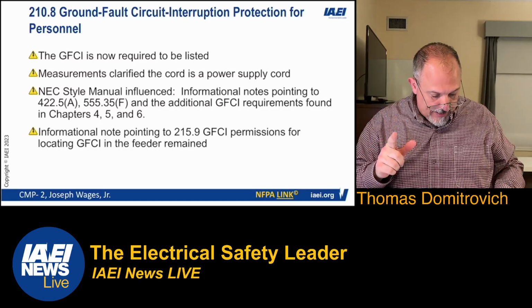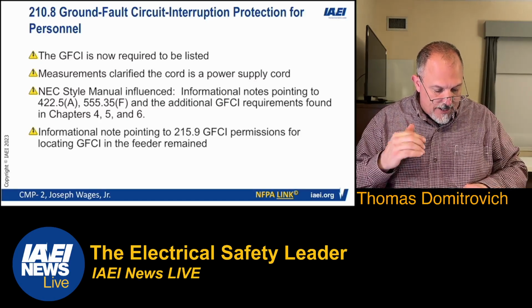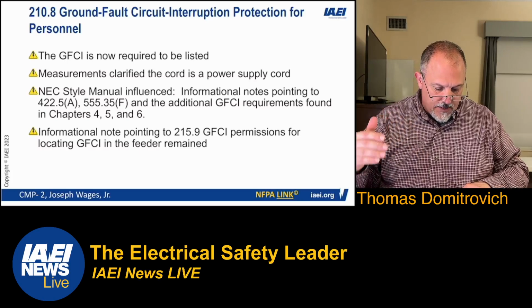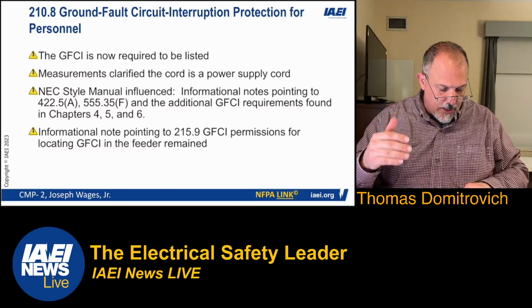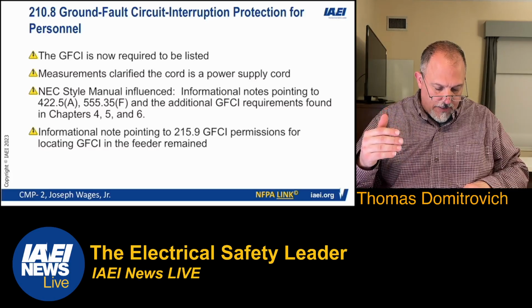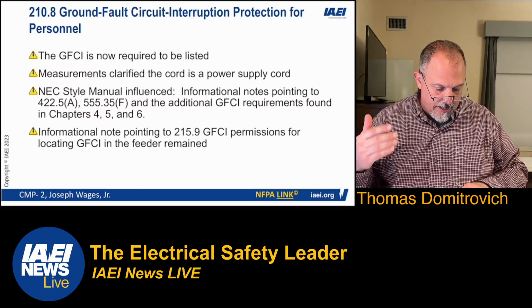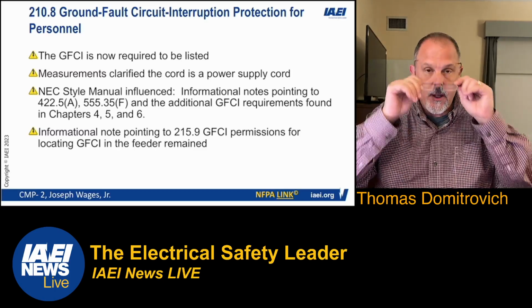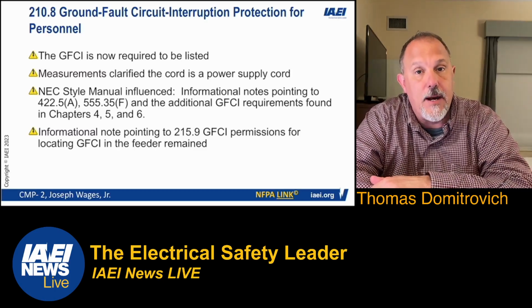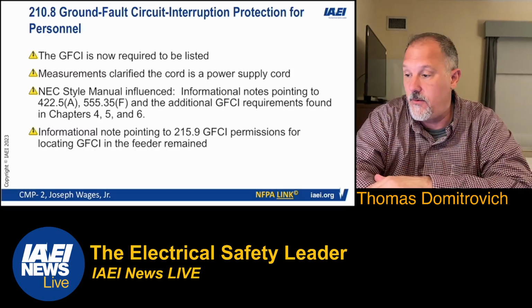The other thing that we did was, in the next paragraph, where we say that for the purposes of this section, the distance from the receptacles shall be measured as the shortest path the power supply cord, not supply cord connected to the receptacle, would follow. So we clarified that it is a power supply cord that is plugged into the receptacle.